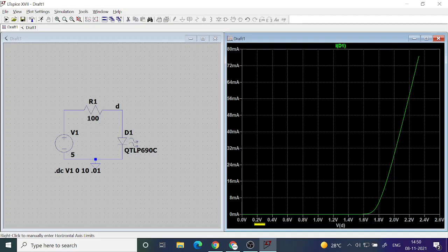Of course a multimeter will give you any voltage, but to see visually on a CRO that there is a change in the voltage, at least of the order of 1 milliampere current should flow, because our resistances are say 100 ohm or 1 kilo ohm, etc. If the current is less than 1 milliampere flowing through 1 kilo ohm, the voltage drop across the resistance is less than 1 volt. So it won't be appreciably noticeable. Is that clear? Yes, sir.